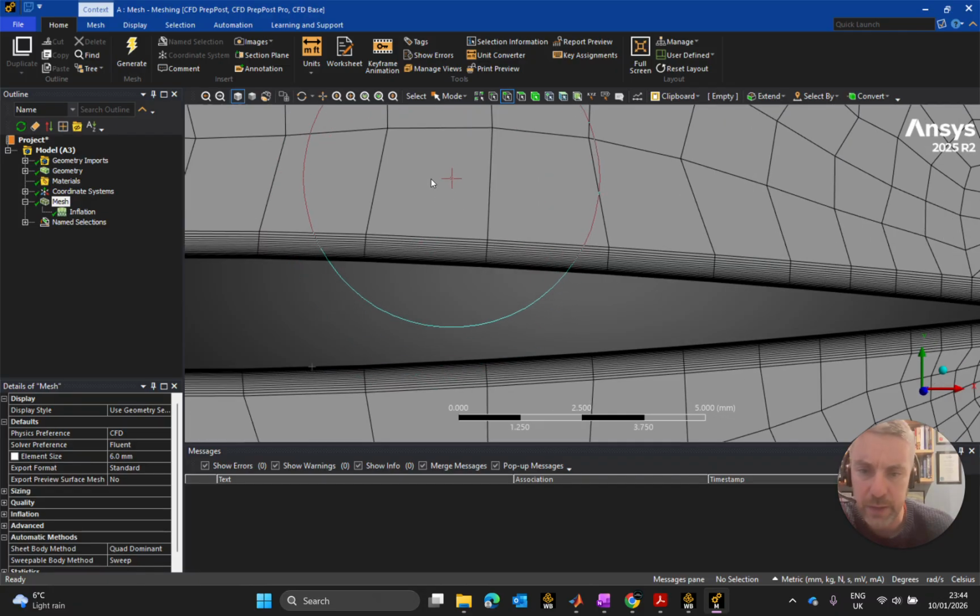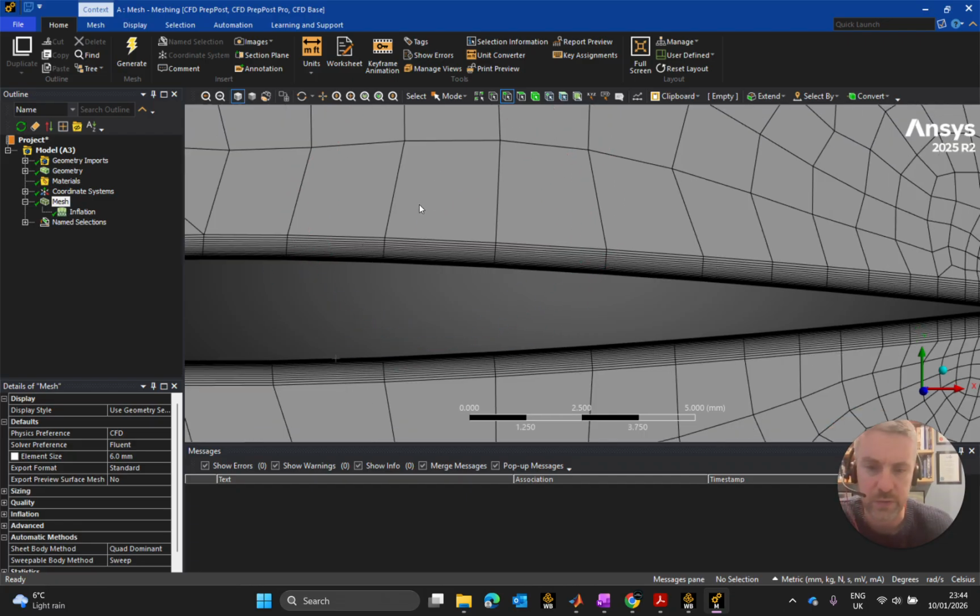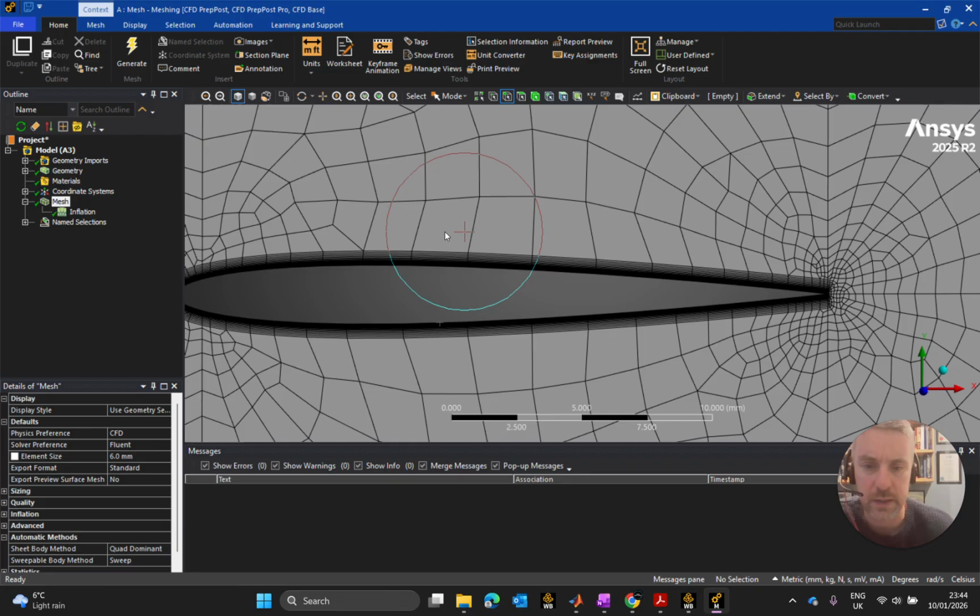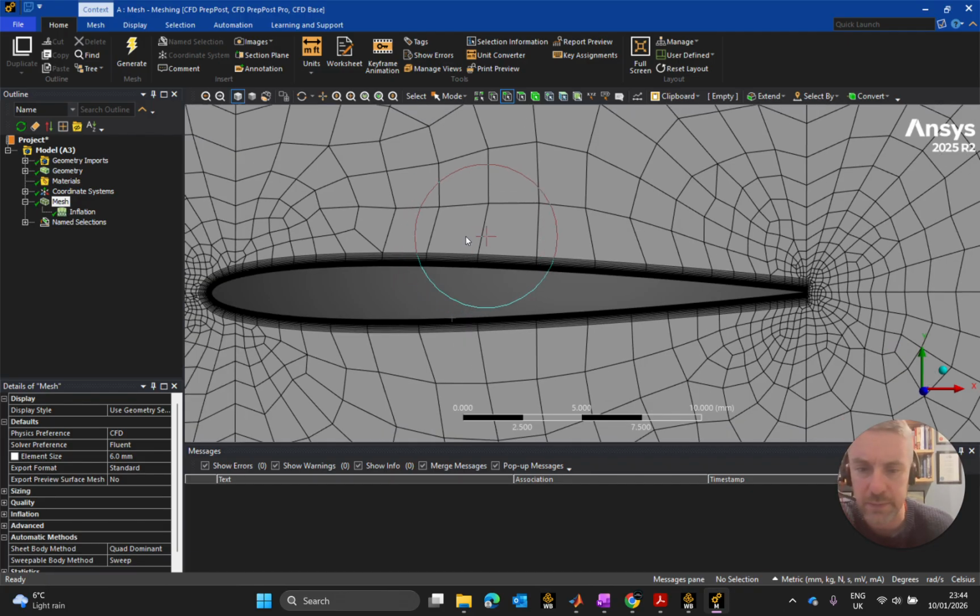Because of such a jump, the pressure and velocity here are going to be so different at the centroid of that, so different from the velocity and pressure at the centroid of this one, that we're missing so much of what's happening in here, which is still a very influential region. We could be looking at the likes of separation bubbles and all types of things up there, even though they really should only be happening down here. If the bubble bursts, you'd see the effect up there. And burst bubbles are something that we definitely want to be able to find because it's something we need to fix if it's there.